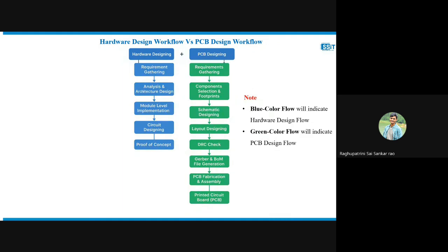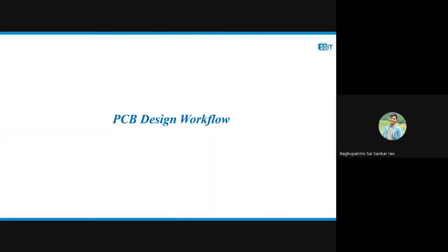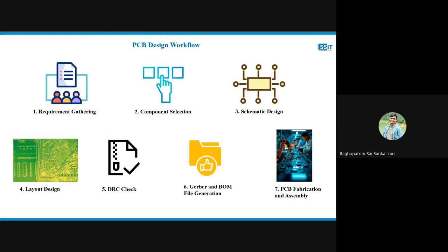In many companies, both of them come under a single person. In a few companies, based on the size of the teams as well as the capacity of the project, there will be individual persons too. And coming to the PCB design workflow, as we discussed, there will be requirements gathering, component selection, schematic design, layout design, DRC check, Gerber, as well as PCB fabrication.